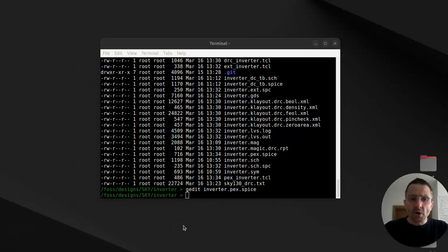Hi, in this video I will show you how to make a post layout simulation of our inverter. For that we will start from our folder which we already know. There are several different files in it. The most important now is the inverter.pex.spice, which is the new netlist, which includes the parasitic components of the layout, which are resistors and capacitors.